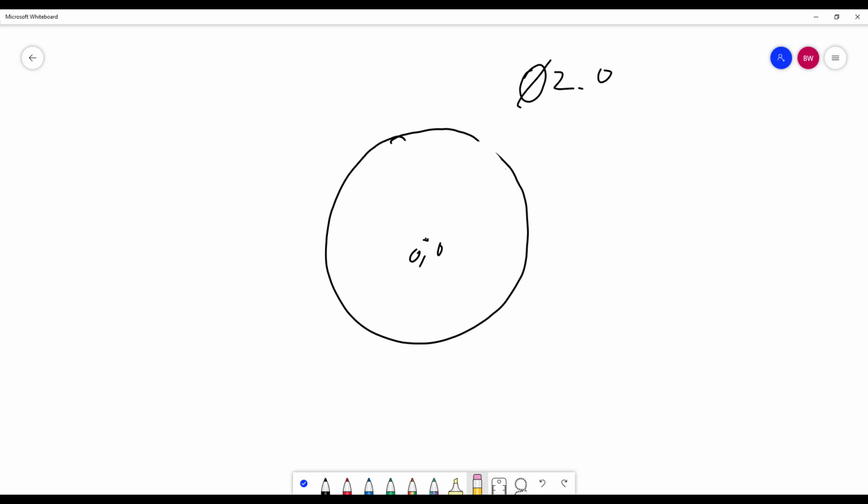Now, this is a 2-inch diameter circle. I'm going to program in quadrants just to show this. Okay, so let's turn the comp on. We need to plunge over here, and we need to move to right here. Okay, let's say we are using the 1/2-inch diameter end mill. Okay, if we look at our code for this, I'm not going to go with the plunging, the Z minus. I'm just going to focus on, we're already there. We're going to go